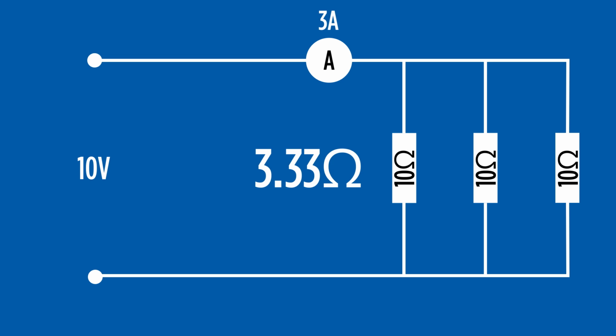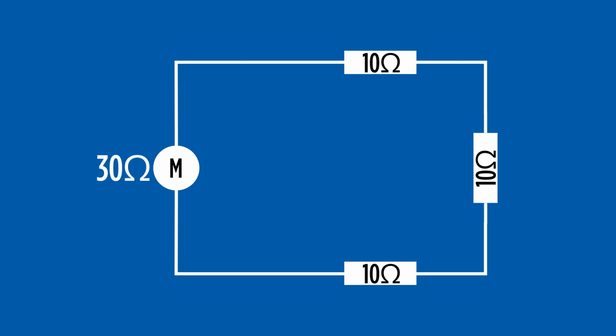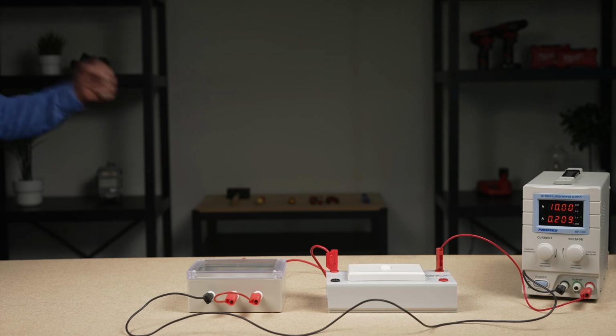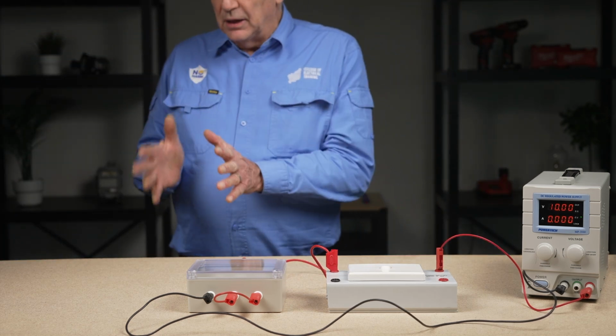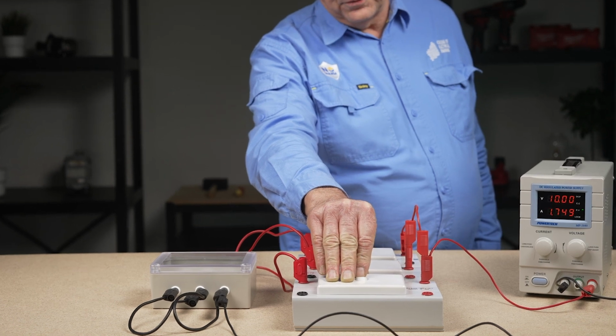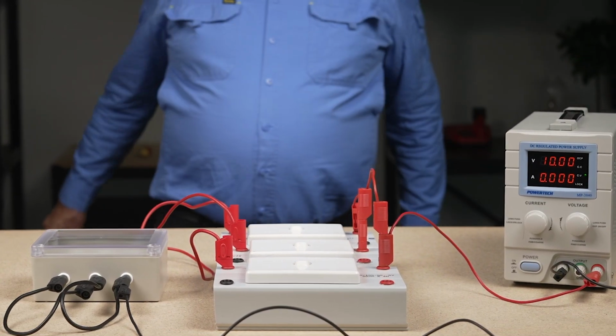In a series circuit, the addition of resistive components increases total circuit resistance. Here, the opposite occurs. The more resistors inserted in parallel, the lower the overall circuit resistance. In a series circuit, an open circuit resistor will cause the circuit current to stop. In a parallel circuit, an open circuit resistor will cause a resistance rise and current drop.